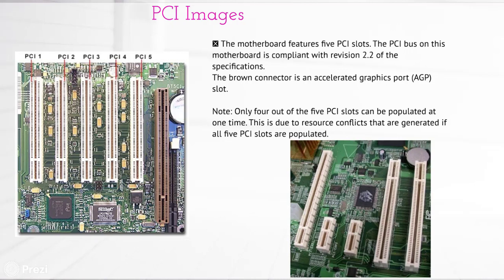this one. The PCI, or Peripheral Component Interconnect, is an interconnection system between a microprocessor and attached devices in which expansion slots are spaced closely for high-speed operation. Using the PCI, a computer can support both new PCI cards while continuing to support industry standard architecture, or ISA, expansion cards, which is an older standard. The PCI uses all active paths to transmit both address and data signals, sending the address on one clock cycle and data on the next.